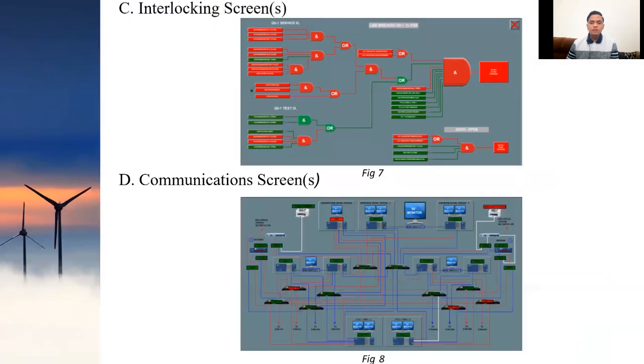Individual bay views also allow the authorized user to initiate commands for the controllable equipment. So next is the interlocking screen. The screen is responsible for giving in-depth information regarding the interlocking logic of controllable equipment. It also depicts the real-time information about the interlock allowed gate and or circuit that facilitates easy identification and marking of the unspecified interlocking condition blocking the equipment from operating.